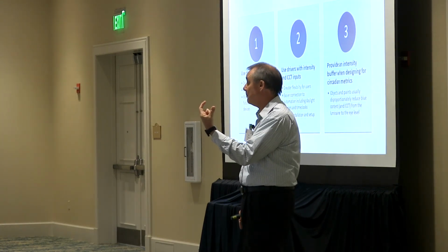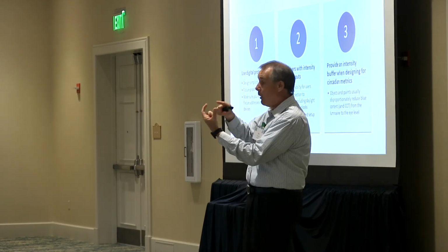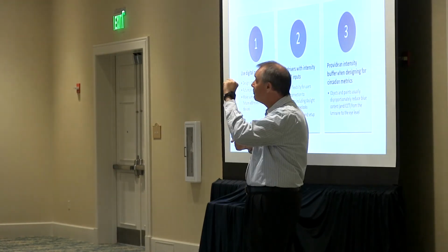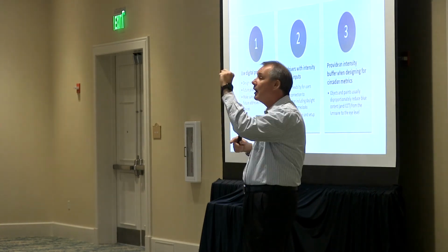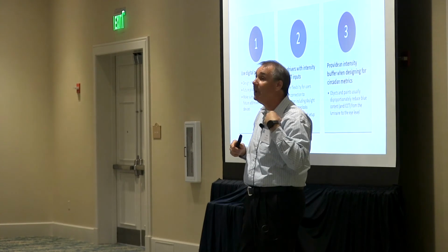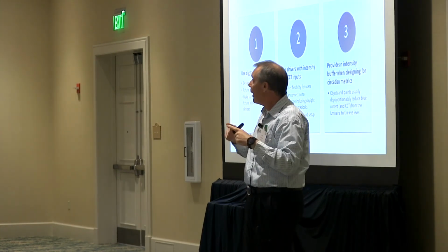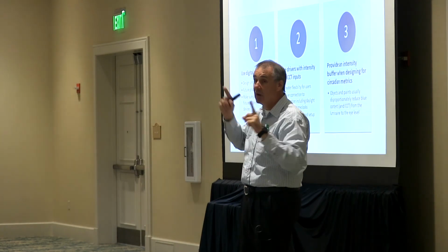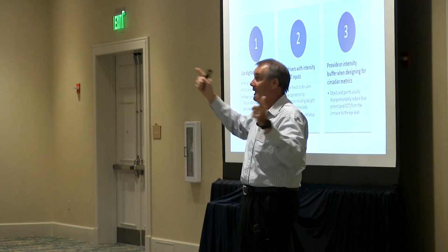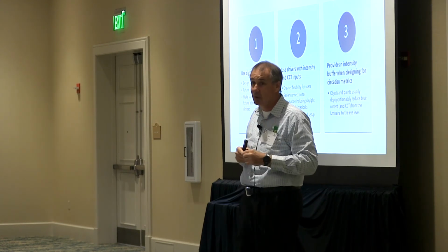One MacAdam ellipse, the population cannot see a difference. However, the ellipse is much narrower in the color direction. What that means is we easily see differences in color. So any voltage drop along a 0 to 10 volt wire may not be noticeable in intensity, but it sure is going to be noticeable in color.